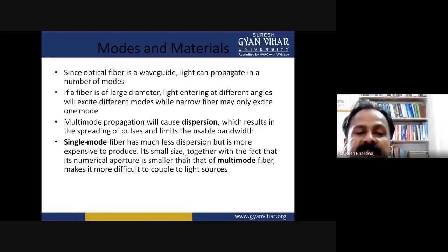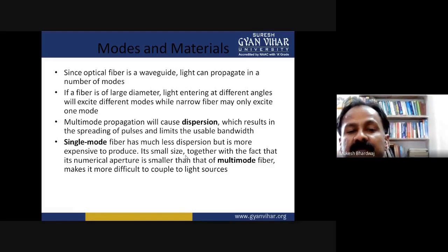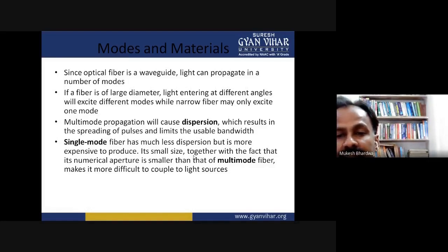Multimode step index fiber. Multimode step index fiber may be fabricated from either multi-component glass compounds or doped silica. These fibers can have reasonably large core diameters and large numerical apertures to facilitate efficient coupling to an incoherent light source, such as an LED.